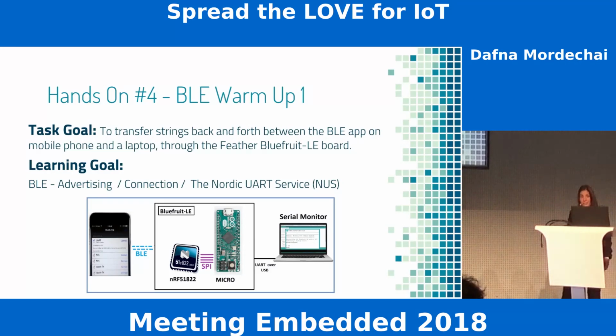So now we went back. We did 2 warm-up exercises, and then the final exercise for the workshop. The first warm-up exercise was about transferring strings back and forth from the mobile phone to their Arduino serial port, over Bluetooth Low Energy with this device. The goal was to start working with Bluetooth Low Energy, to see advertising, and to have a connection with the mobile app. I also sent them to read about the Nordic UART service, which is a logical UART. It's a service that has 2 characteristics, one is TX, for transferring, and one is RX.